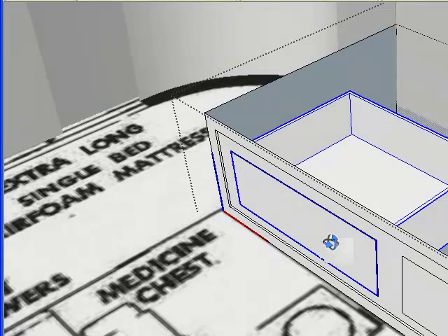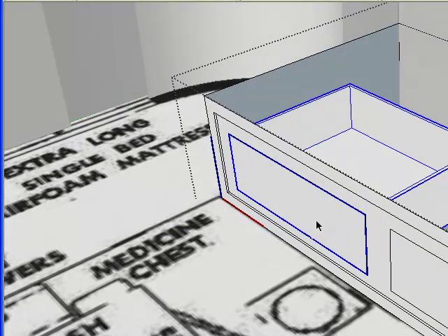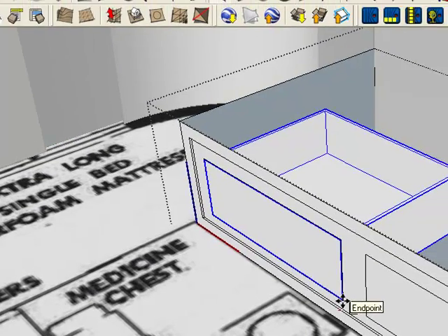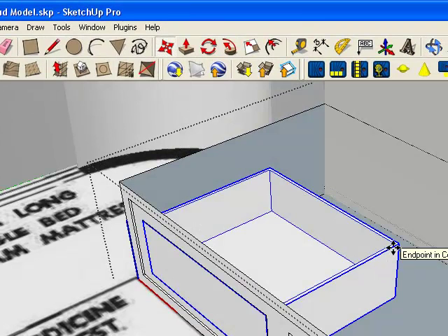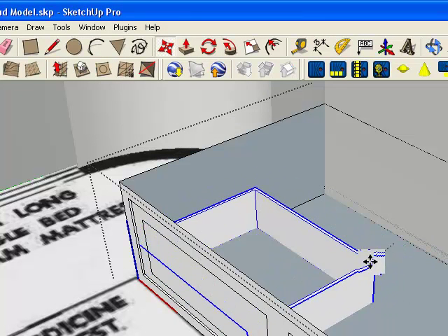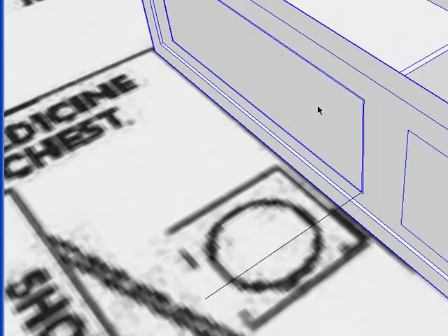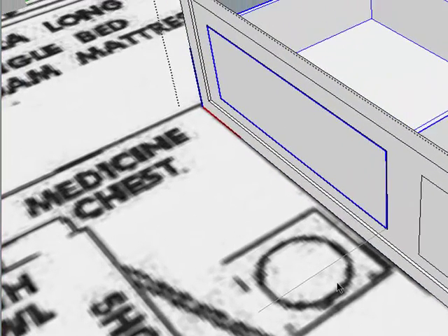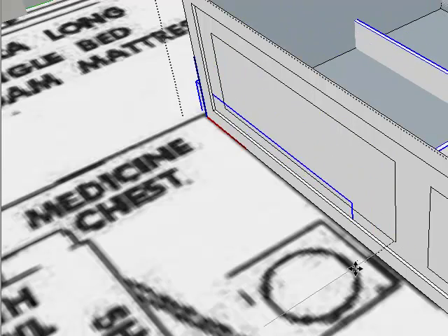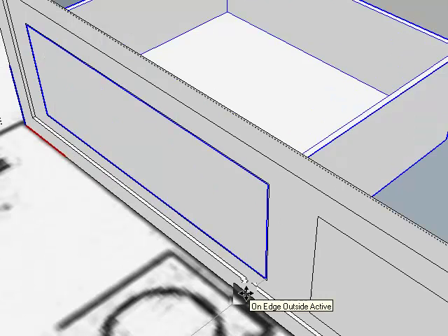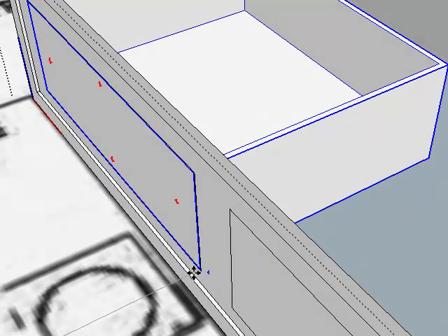So if I click on the component, once I have the drawer created, I can click on the Move tool, grab one corner, and I can work from here or work from back here. Let's work from back here. If I click and hold with my left mouse, I can actually, sorry. Sometimes I like to do this too if I'm having a little problem. What I'm going to do is deselect all of this and draw a line from the corner of that straight out on my axis and click. Now let's click on the drawer again. So we have the drawer highlighted. Use the move tool, and I can slide it out along this line. Alright. That is not going the direction I want it to go for some reason here.